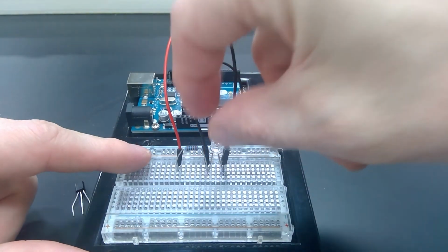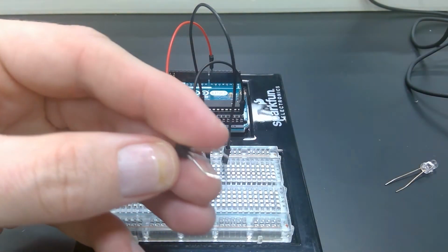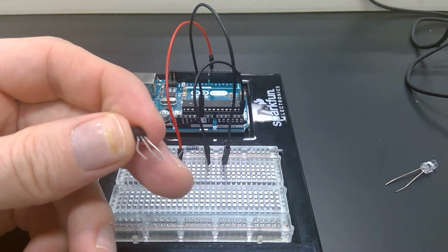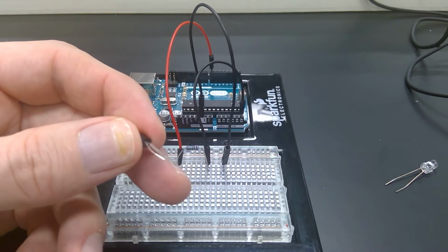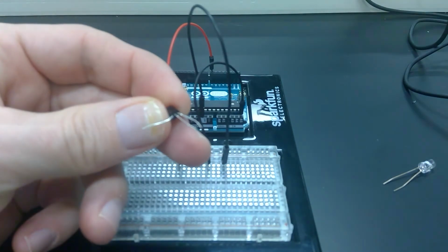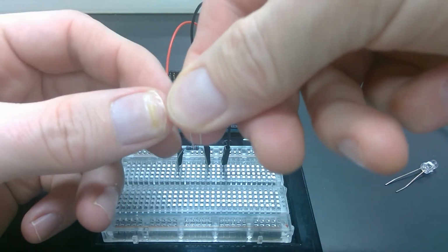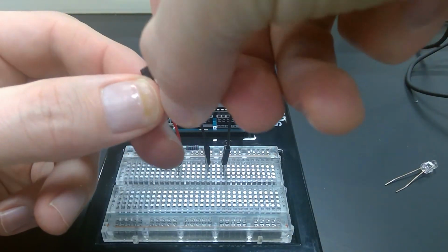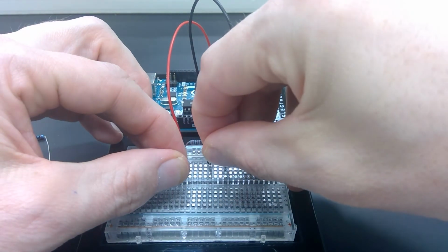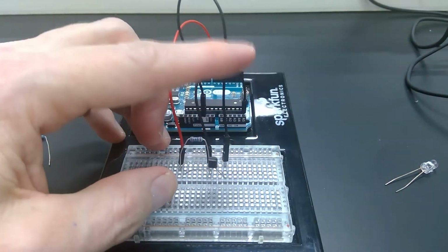So I'm taking the LED circuit away, pop out the LED, and now I've got to pop the temperature sensor in. One thing is that the temperature sensor doesn't have 2 pins, it has 3. And I've got to look at the data sheet to see which 2 I want to use. It turns out that this pin over here is so you can build a circuit and calibrate it a little bit better. We're not going to use it. I'll just bend it out of the way. Don't do that if you can help it. And then for these 2 pins, the middle one gets connected to the resistor and the wire going to the analog pin, and the one on the right gets connected to ground, like this.